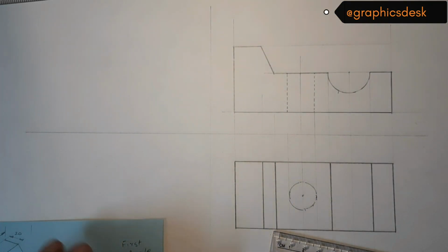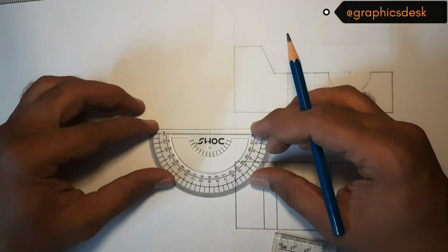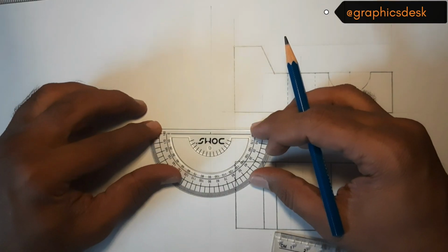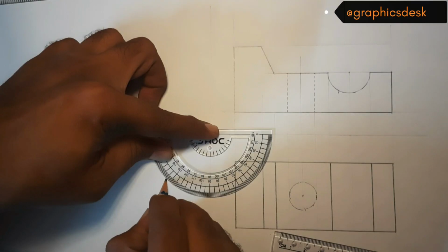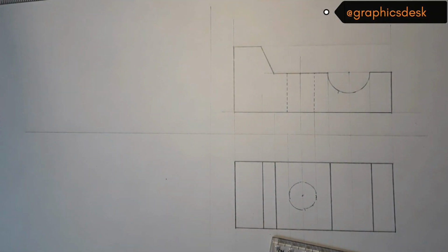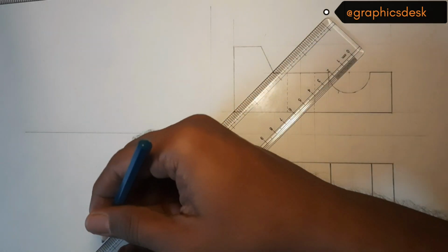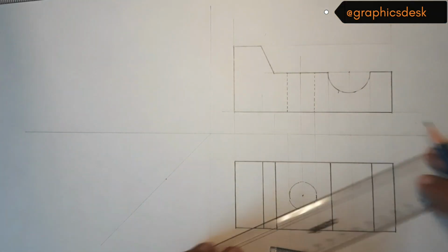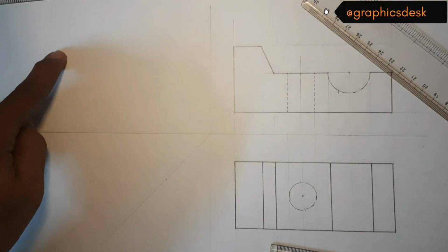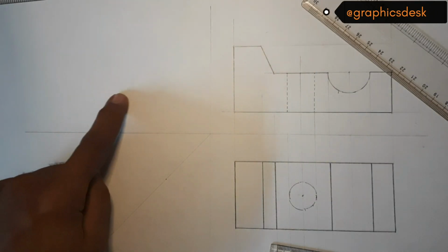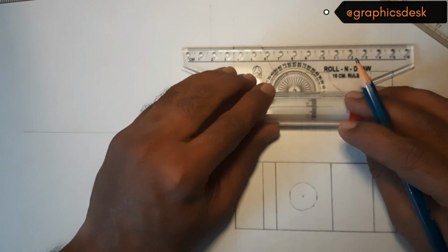So what I'll do is I'll mark a 45-degree line over here from this point, where our vertical line and XY are meeting. Okay, so this is that line. And now these projections will come until this point and will go vertically up, giving us the intersection to have our right hand side view. So let me mark the horizontal projections first.